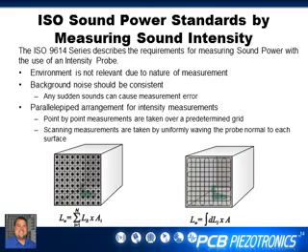The point by point measurement is more accurate. The nice part about that is also some data that can fall out of that is source localization. So if you have a particular noise source, a part of the structure or the source that you're interested in the sound of, using the point by point measurement, you can get a source localization.